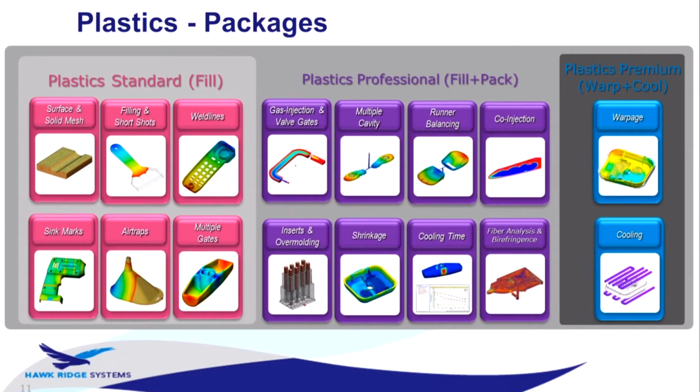It's going to give you an idea of whether you're going to be able to fill the cavity with the settings you have. You don't want to get a short shot. It's going to give you some insight into the location of sink marks and air traps. It's going to let you experiment with different gate positions to see which one is going to fill the part most effectively.